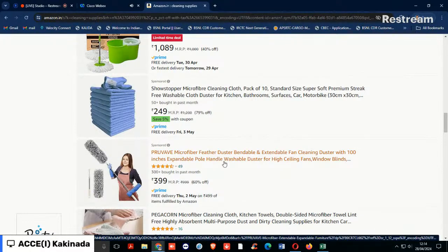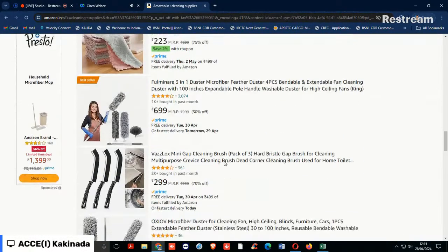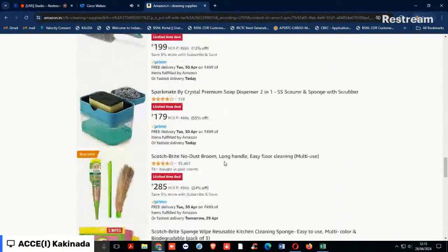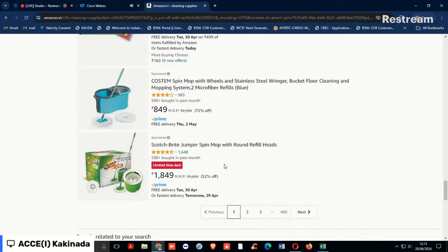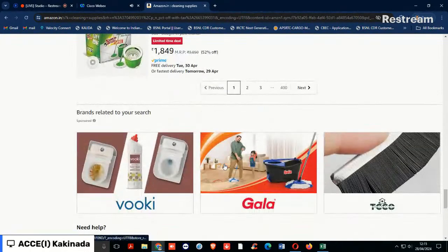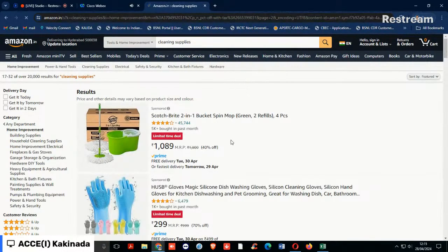These PVC conduits are a distinct material that we place in the concrete above the steel reinforcement, but that is below the neutral axis. At the supports, we have a double reinforced section. Your neutral axis is almost at the mid surface. Your entire PVC pipe is within the tension zone only. That leads to the development of tension cracks after hardening and shrinkage of the concrete due to thermal expansion stresses. These are very dangerous.